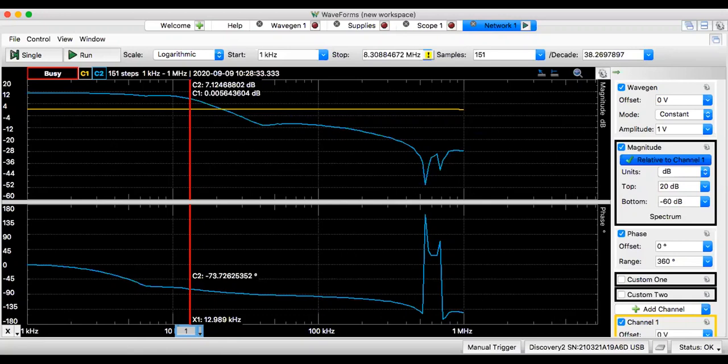So number one issue is saturation. Number two is bandwidth. If you want to have an amplifier, the input frequency in this case has to be below that frequency. Anything above will be greatly attenuated, reducing the strength.